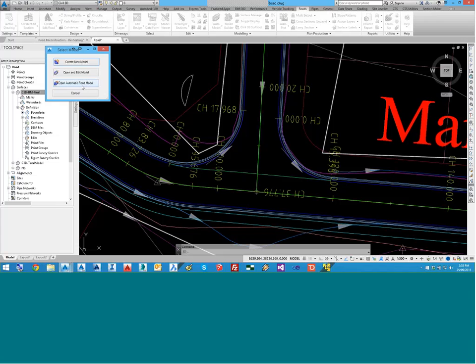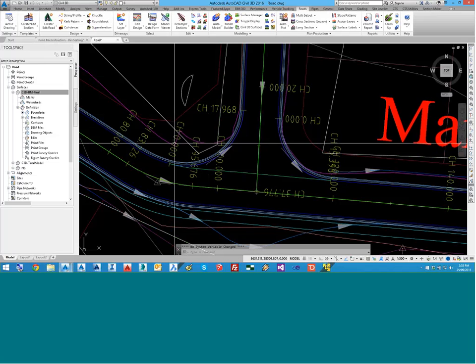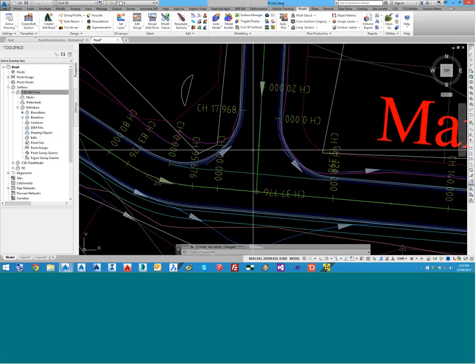You could also use Model Builder to trim out those overlaps. As I said, you could exclude the batter between a certain region as well. Or the third option is you change your design to ensure that no overlaps occur, whether changing the slope or fixing up the geometry of the project.